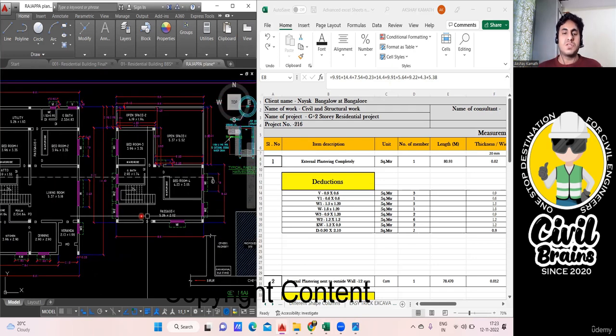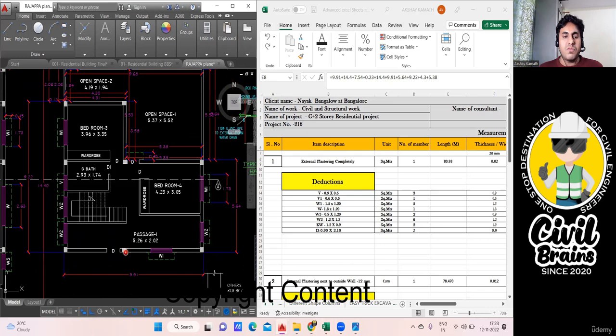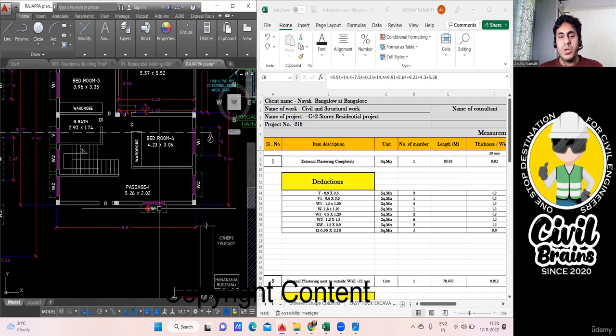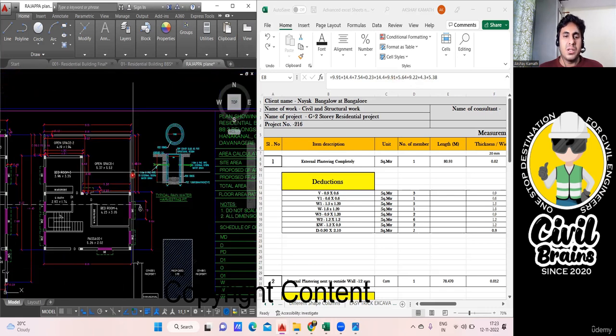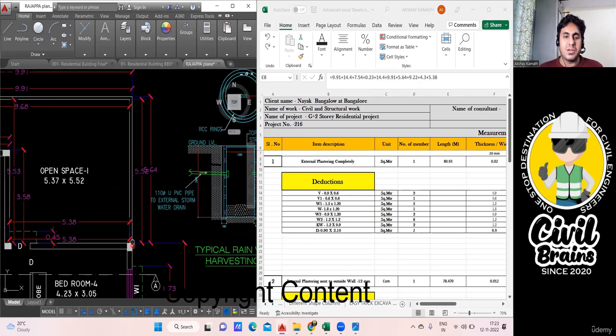Now let me take you to the first floor. Now come to the first floor. So in the first floor, I'll start from here. From this outer to this outer, how much is it? 9.91. So I've already written 9.91. Okay. Now again, from this outer to this outer, I'll not take this part. This comes under the parapet. I'll teach you later. Okay.